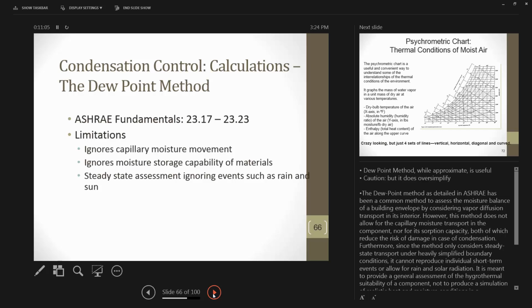The 10 times relationship, even in ASHRAE, in what we talked about, ASHRAE 90.1 for energy performance and 62 for IEQ. They actually have a standard for vapor drive, moisture migration, and controlled moisture. Even in the ASHRAE standard currently, in what they recommend, it ignores capillary moisture movement. So a lot of times you'll have that moisture movement that wicks up through the material.